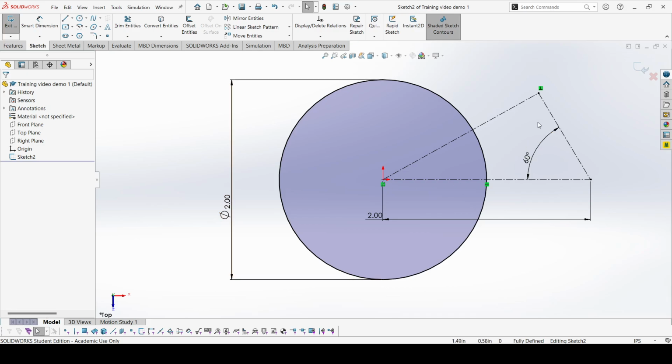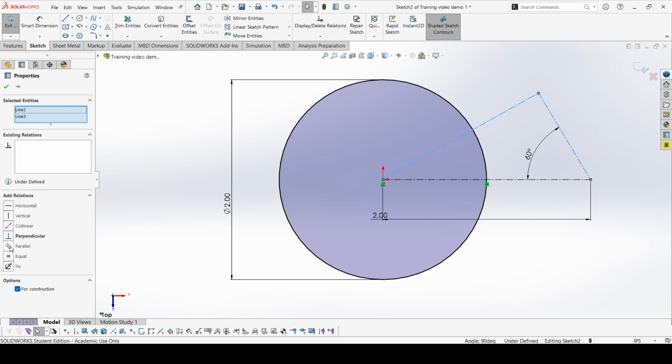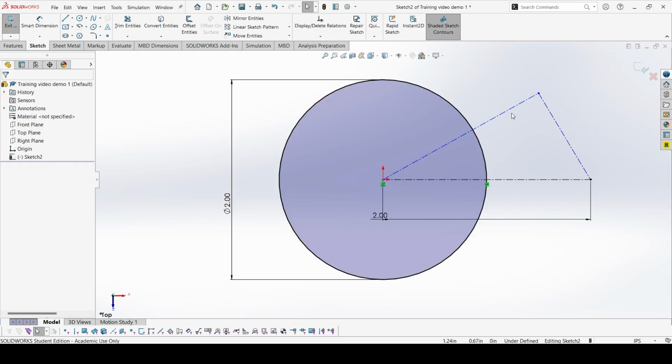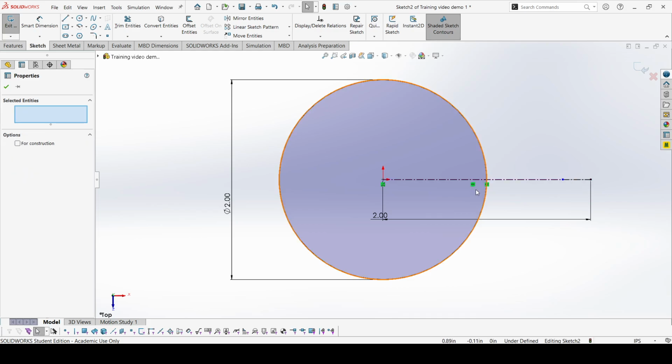Pretty simple. Now, another thing, let me make this not perpendicular so I can show you something even cooler. I can make these, well, I can't make them parallel. That'll cause an error. You notice that sketch is overdefined. This item is unsolvable. I can't make them collinear. Because of this angle, I suppose they could be parallel, but if you'll notice, they will collapse into that line. So yeah, they're not going to be parallel. Horizontal, they collapse into that line. Yeah, let me get rid of those.